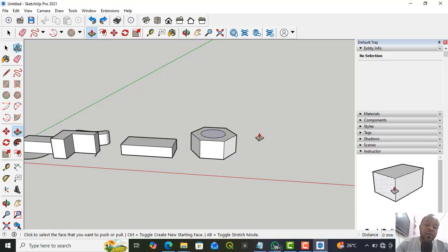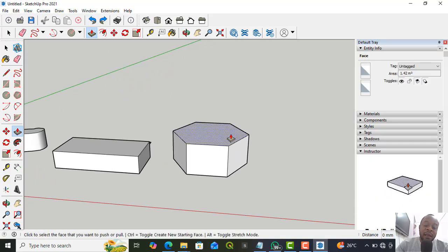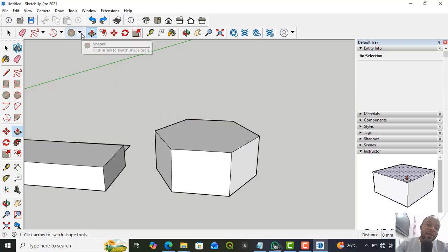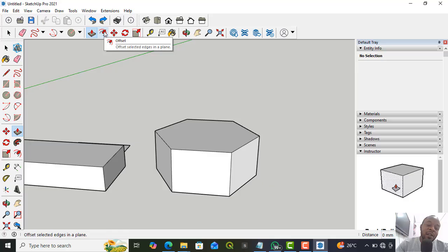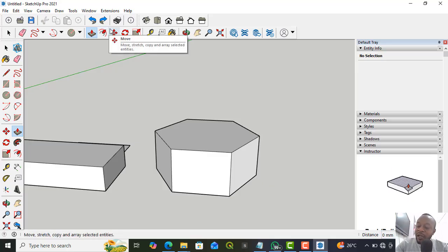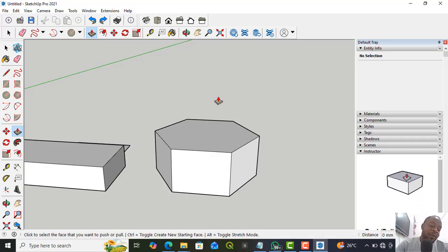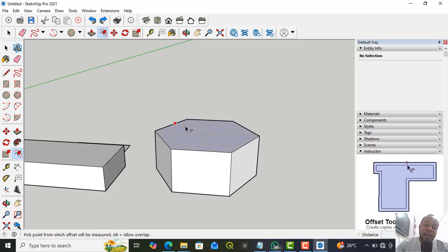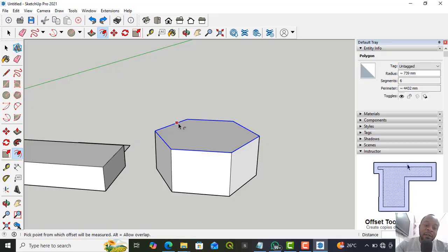All right, so now, for example, just now I wanted to create another shape here so that I can push it in, right? And then I pick another circle to draw. Like the word offset in AutoCAD or any other software that you're using, they are offsetting an object parallel at a specific distance, right? So I'll click on offset, and then I'll click and drag, so I can specify my offset distance. So let's say I want it to be at the distance of 200.